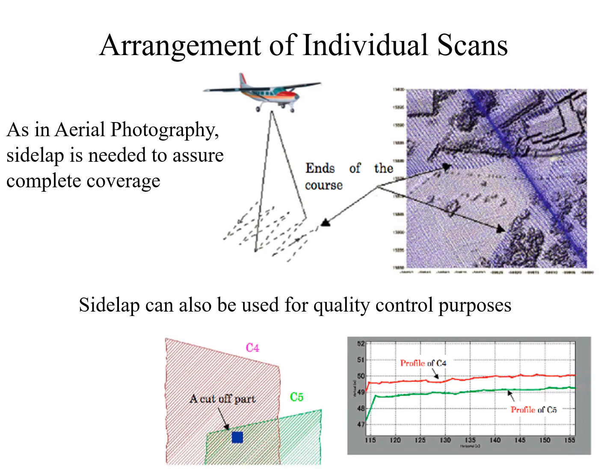As in aerial photography, you need side lap between data passes in order to assure that you have complete coverage. So in the upper right hand, what they're showing you is that dark blue area. That's where you have two lines or two transects overlapping. You have double the density.